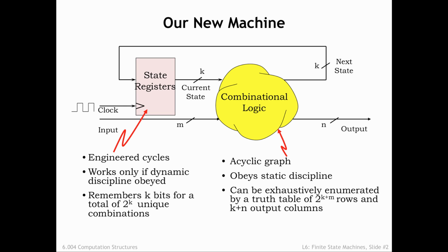As designers, we have several tasks. First, we must decide on what output sequences need to be generated in response to the expected input sequences. A particular input may, in fact, generate a long sequence of output values, or the output may remain unchanged while the input sequence is processed, step by step, where the FSM is remembering the relevant information by updating its internal state. Then we have to develop the functional specification for the logic so it calculates the correct output and next state values. Finally, we need to come up with an actual circuit diagram for the sequential logic system. All the tasks are pretty interesting, so let's get started.